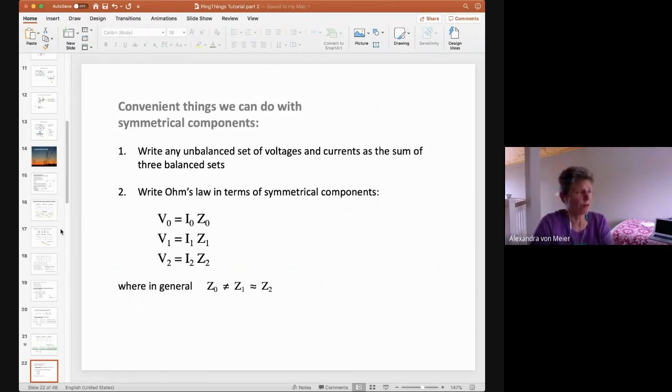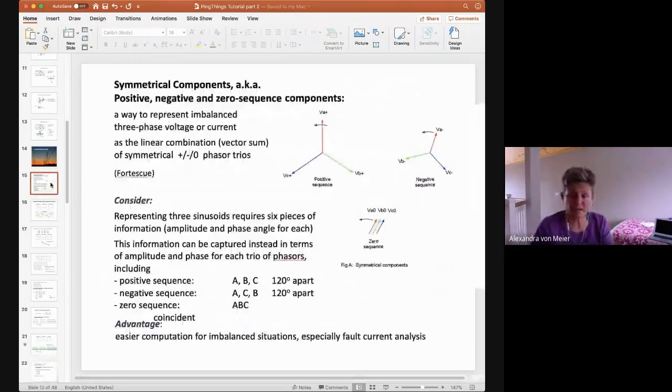Usually it'd measure all 3, but it won't be reporting back all 3 phases individually. It might just say, we've looked at 3 phases, and yeah, there might be a little distortion, but we're telling you what the positive sequence component is, which is the dominant component, so that should be approximately right.